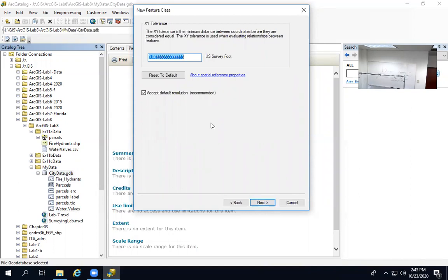Okay, here comes the word, something called tolerance. Since you're not working with CAD, you're working with GIS. And GIS sometimes has some rules that will enable you to map things much better. Tolerance is simply a value of distance or a radius of distance. If you put 4 or 5 points in this same radius, the computer will use it as 1 point. It's like a snapping option.